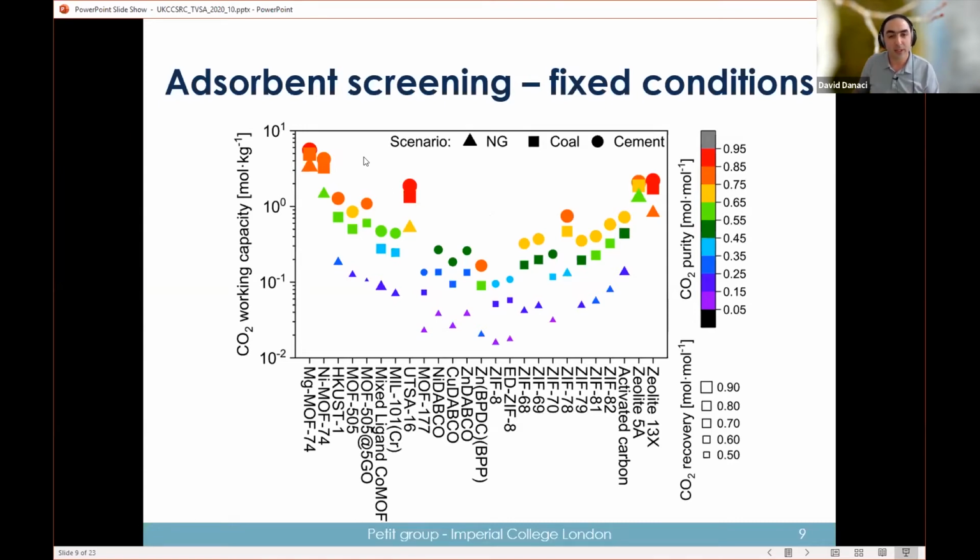And what is very different to the last piece of work on PVSA is that the MOF 74s demonstrate quite excellent performance under TSA conditions. This is not unexpected, as they have a very high enthalpy of adsorption. So you would expect a change in temperature to cause a significant reduction in adsorption and hence good working capacity.